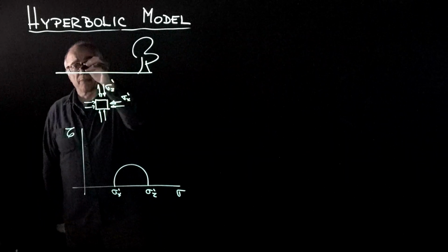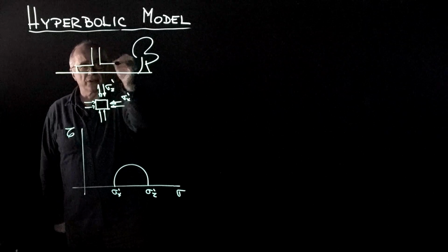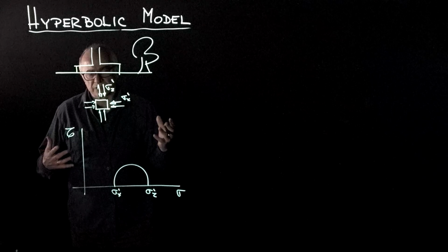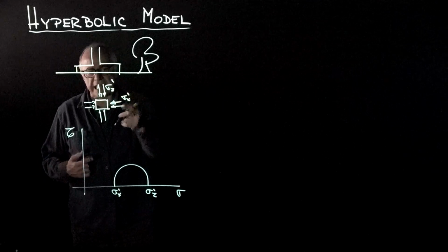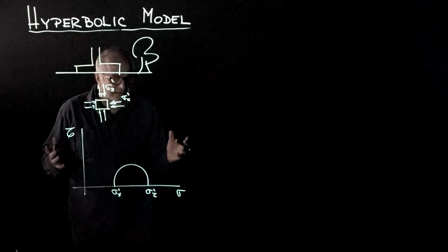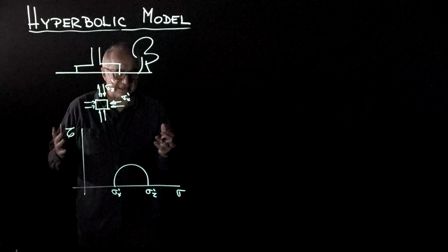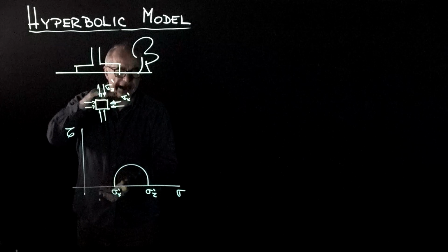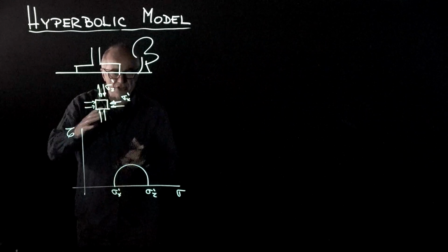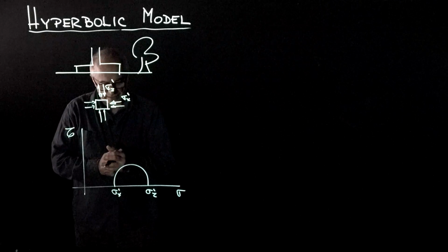Then we're going to apply a footing onto the soil, and this will add additional stress changes, both in Z and in X. In a triaxial test, typically we change one of them at a time. For example, we apply a delta sigma Z or a delta sigma X in axial compression or lateral compression.